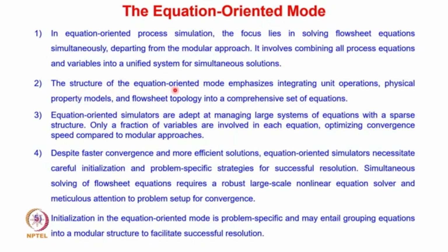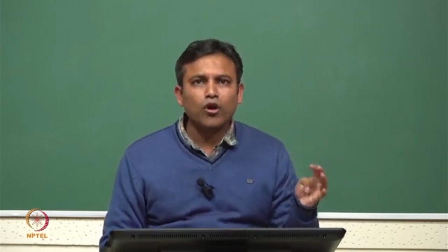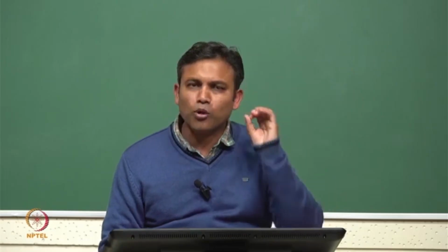The structure of the equation oriented mode emphasizes integrating unit operations, physical property models and flowsheet topology into a comprehensive set of equations. So you can see that in an equation oriented mode, all these equations, including property, the different unit operations, and also the flowsheet topology, including the recycle, are solved together in a simultaneous manner.